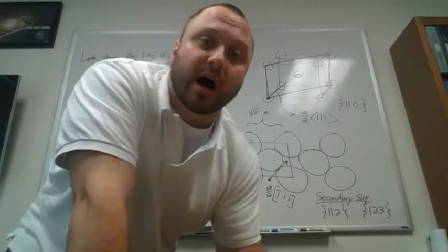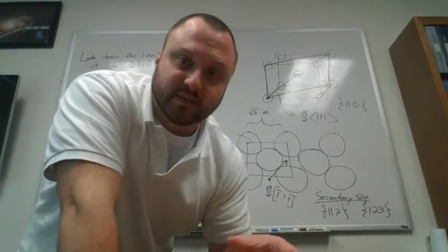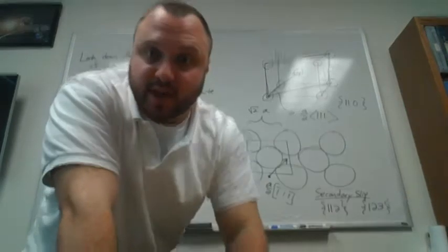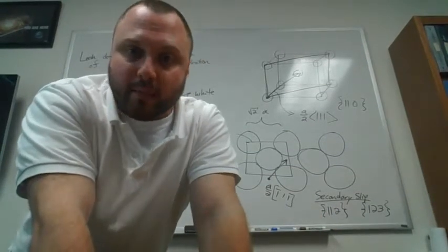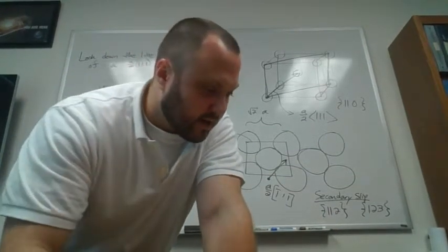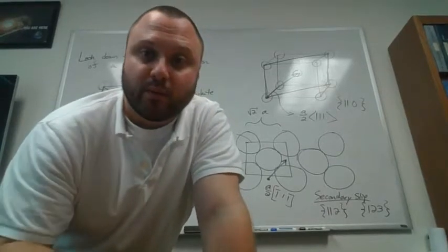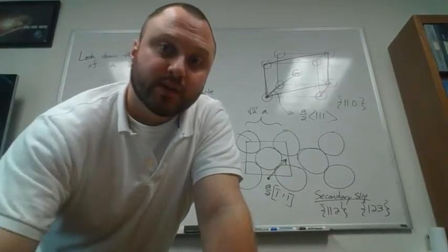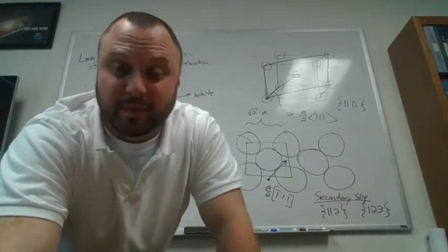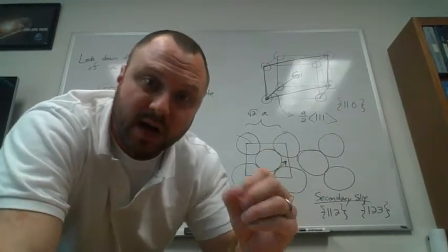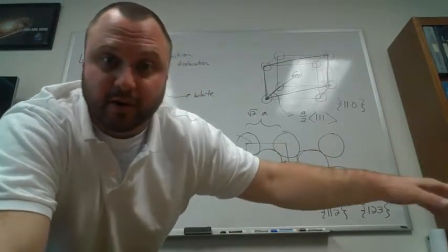When we first derived what the stress and strain field of the atoms around the dislocation would look like, we came up with something saying that they should be displaced in a way that's 1 over r. So the amount you're displaced from the perfect crystal should be really high near the center of the core, and as you get further away, it should get smaller.